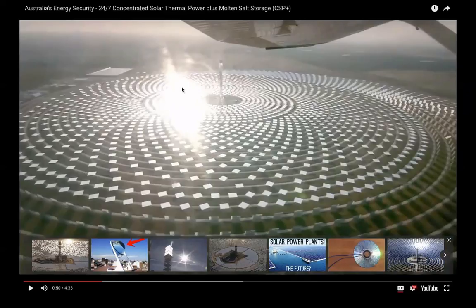The way these are arranged is very carefully calculated in order to ensure many things. For instance, you want to reduce the cost of the system by reducing the number of mirrors used. You also want as much coverage as possible so you don't lose light. You also want to ensure these heliostats don't shadow each other, so they cannot be too close. So it's a very complicated system.